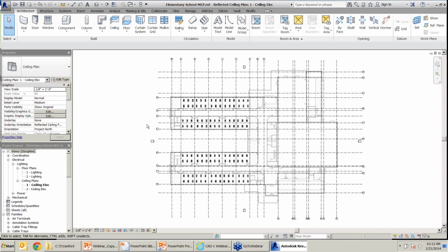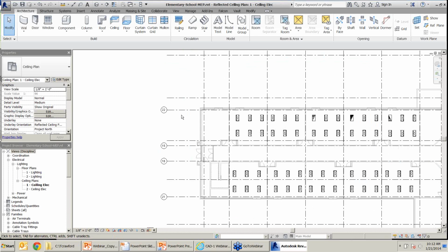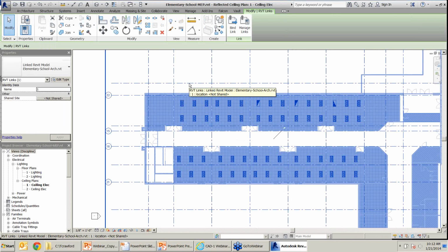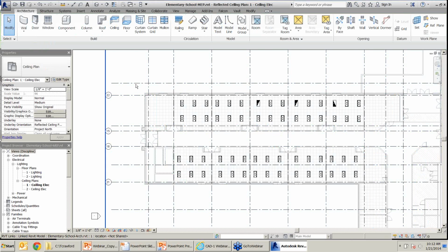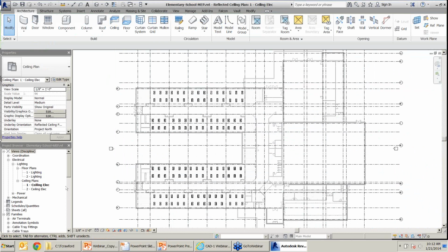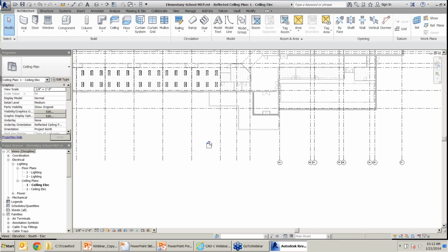You can see there's wings on the left. I have grid lines and I have light fixtures. When we get to the lights, we'll probably focus on this wing, this end of the building. And again, right now, it's one linked file. I don't have anything live in my file except some views. So I need these grid lines. I want to copy these in. But before I do that, I really want to have levels so that I can set up views. I have 2 levels already in my file, but let's take a look at those.